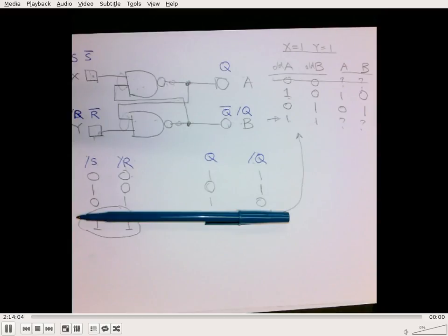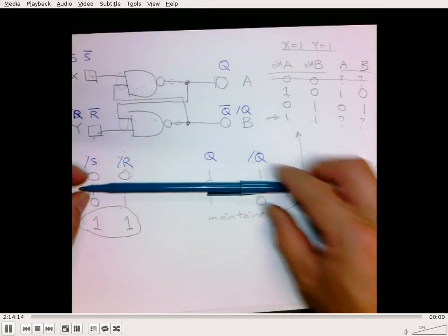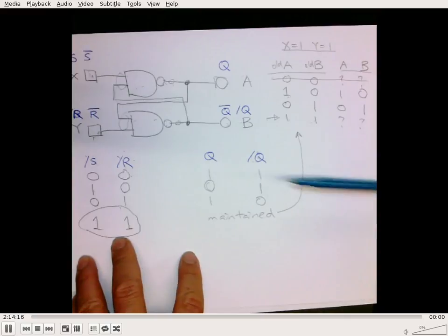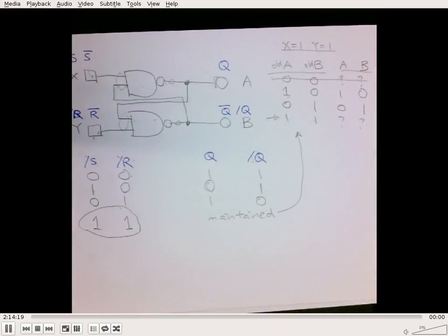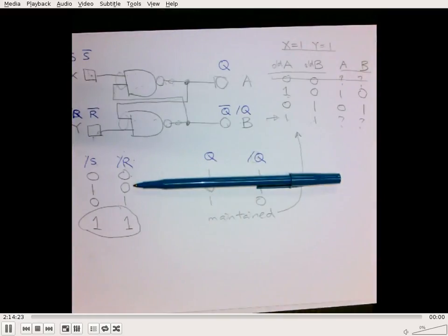It's weird seeing Q on when S and R are both zeros, Q and not Q are both 1. So why is it called not Q if it's not Q? It is just because the top row is not used much, because you normally would not have /S and /R both being zeros. If you take the slash into consideration, a 0 means you want that.